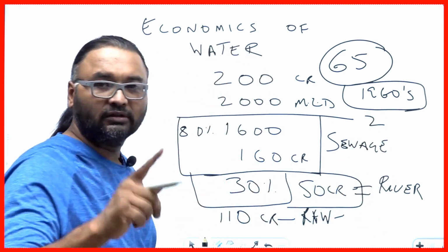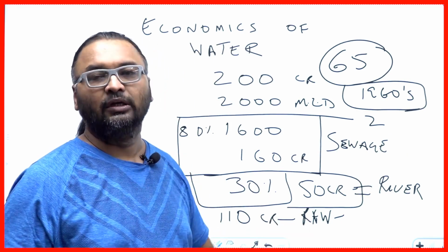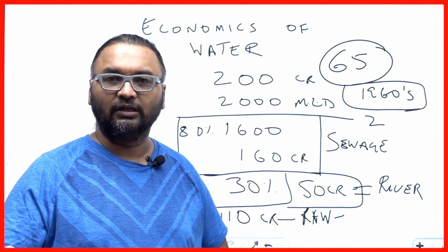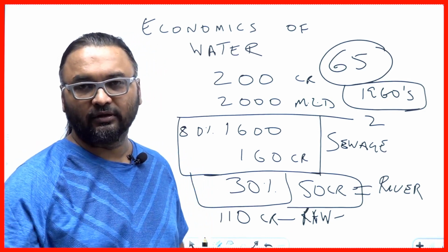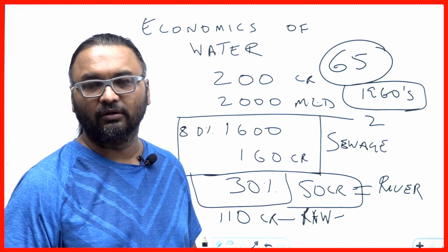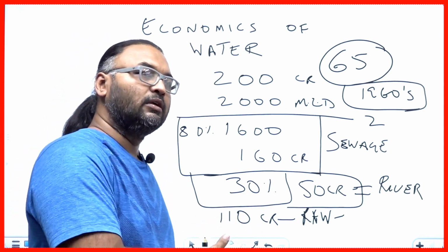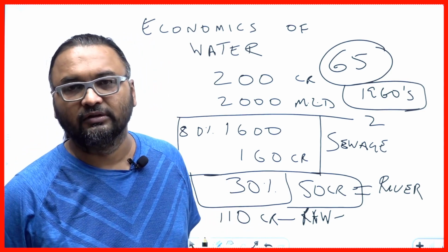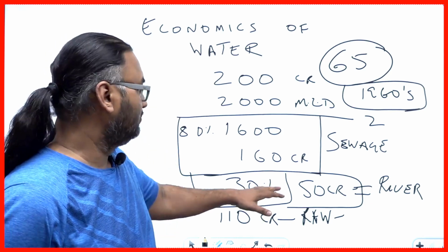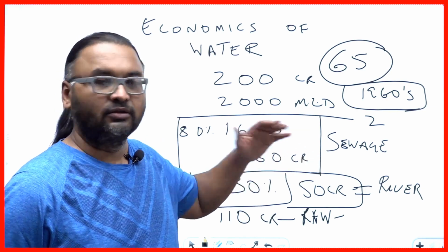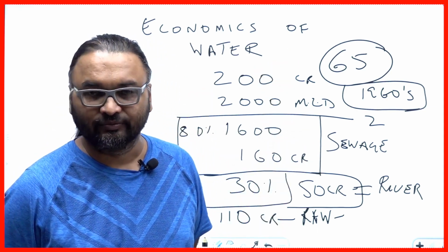The dissolved oxygen that is required for bacteria to process this sewage is normally, let us say, 2 milligrams or some such thing. The dissolved oxygen is supposed to be 2, but about 98% of it is just not there, because sewage has come and overpowered it. So you have BOD levels of 12, 15, and so on.